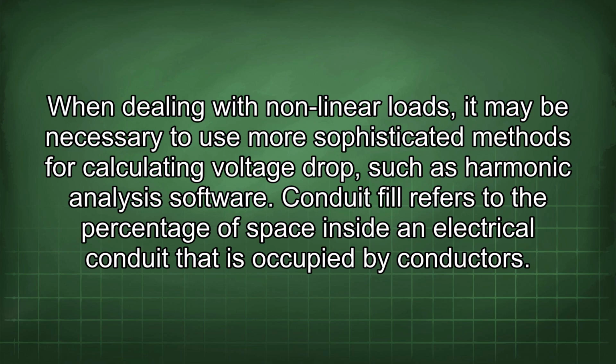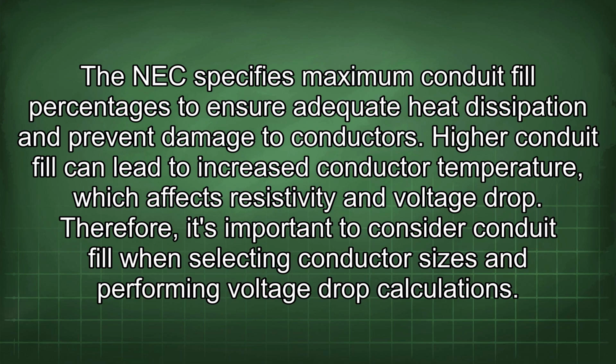Conduit fill refers to the percentage of space inside an electrical conduit that is occupied by conductors. The NEC specifies maximum conduit fill percentages to ensure adequate heat dissipation and prevent damage to conductors. Higher conduit fill can lead to increased conductor temperature, which affects resistivity and voltage drop. Therefore, it's important to consider conduit fill when selecting conductor sizes and performing voltage drop calculations.